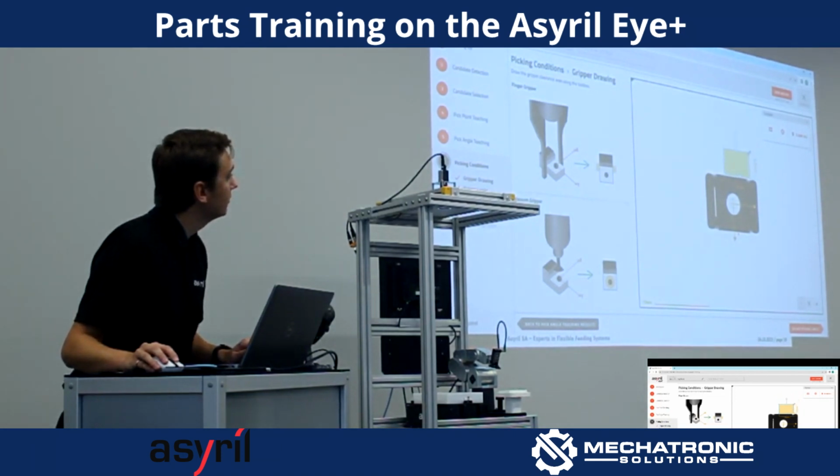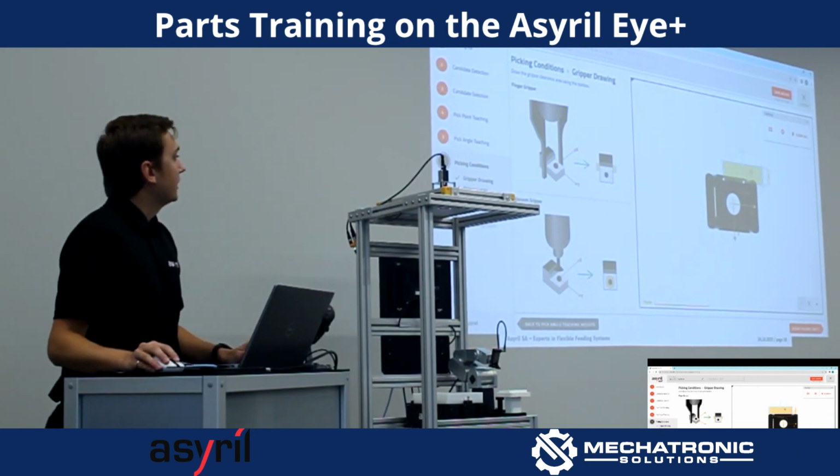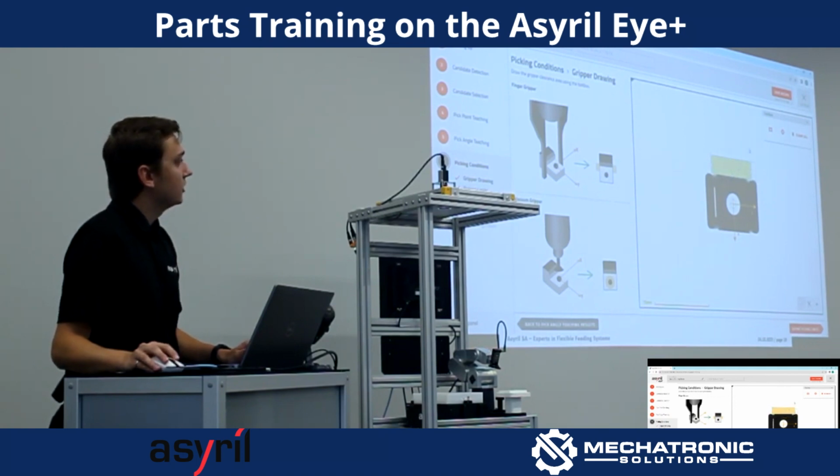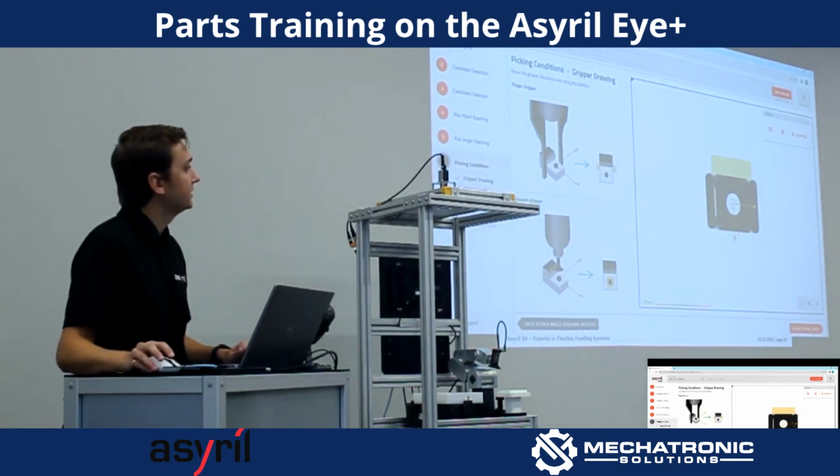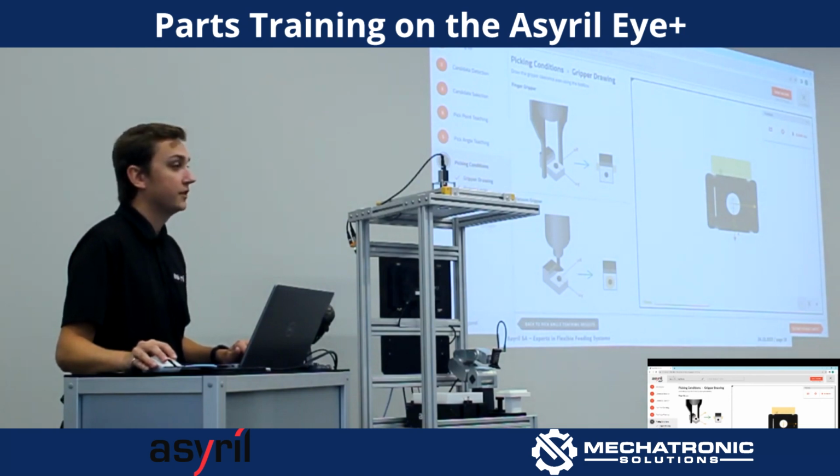I don't really know. We'll just go with that. Sure. So then you can lock it on to the middle of where your pick point is. And this exclusion zone will designate this part as not pickable if there is another part detected within this range here. That's to avoid gripper collisions and robot collisions.